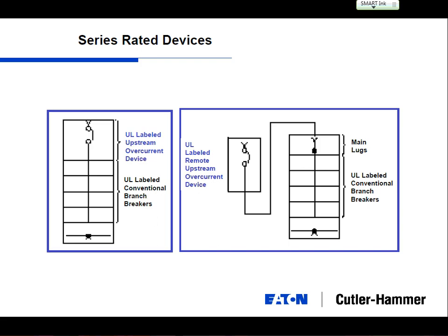Even if I open this breaker to work on it, if you look at the back side of this, you've got 480 volts right here at the top. The breaker's in the middle, so you're opening the circuit in the middle, but here, you still have 480 volts. And there's no way around that.